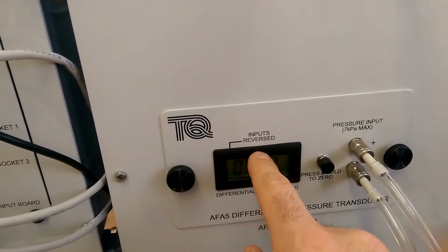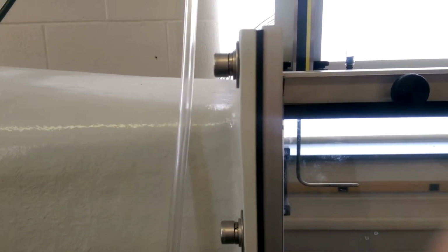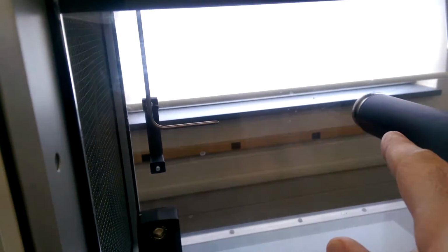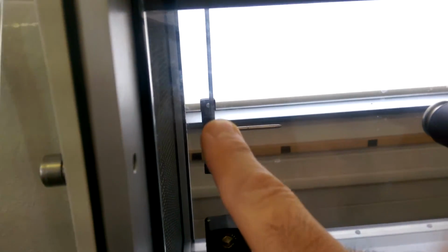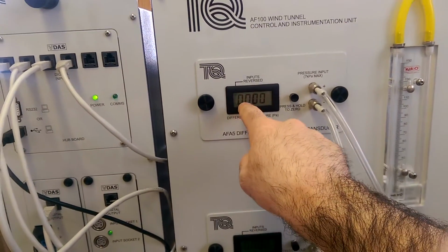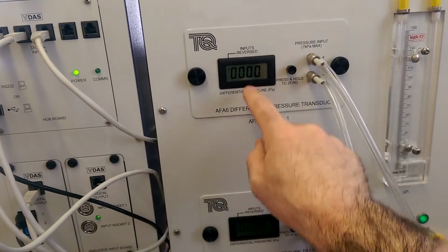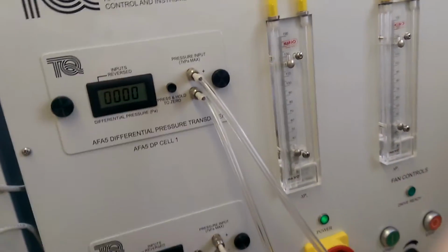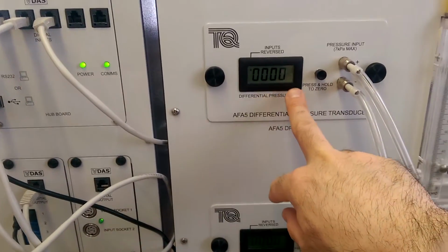This digital manometer is measuring the pressure difference across the pitot tube here, which is moving vertically up and down behind the wake that's created by the airflow over the cylinder. So what's going to happen is that you're going to move it from a top position, move it down until you start just getting into the wake. That should be a point where this velocity starts to change, to a point that this pressure is slightly below this pressure. Try to position the pitot tube such that these two pressures are approximately equal.